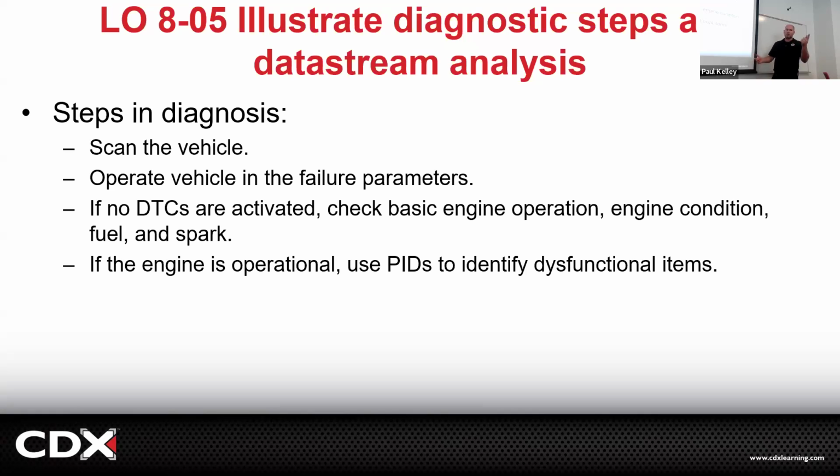I'm actually going to be posting a video on Monday or Tuesday of a misfire that you guys might be interested in. This is a student who's saying, hey, I got a misfire code. And I'm like, what's the code? And I think it was P0302 and 303. And I'm like, all right, so cylinder 2 and 3, that's interesting. They're both misfiring and they're next to each other, but okay. I looked on the forums. I tried spark plugs. I tried this. I tried, can I switch injectors?